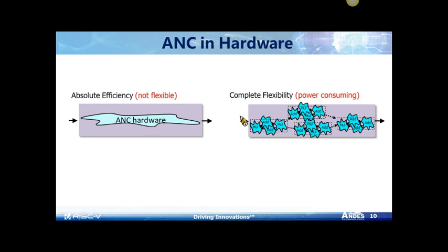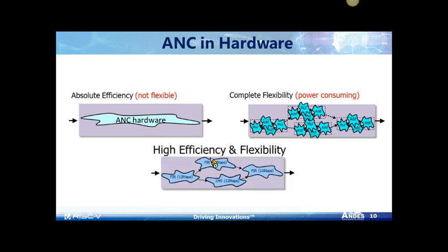That's why in the ACE solution we make the FIR filter and LMS to be our arithmetic unit. If you fully design in hardware, then it will lose the flexibility. If you run it with baseline instructions, it will cost too much power. Here, we introduce an ACE solution with high efficiency and flexibility.